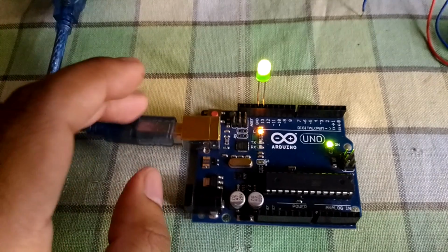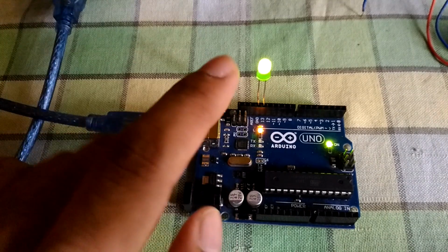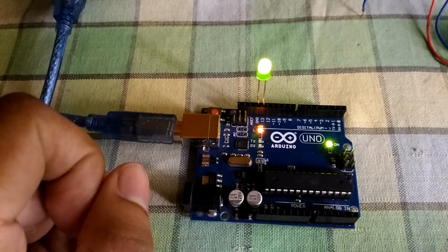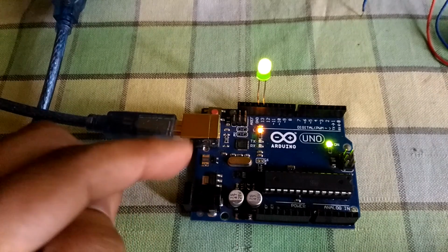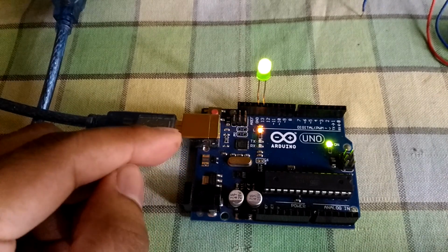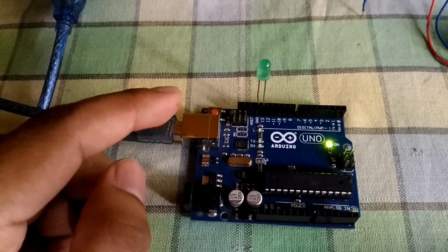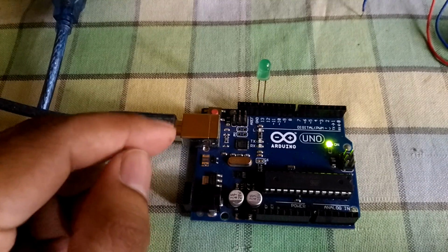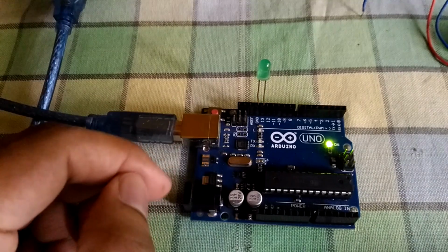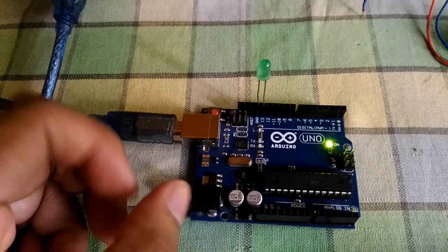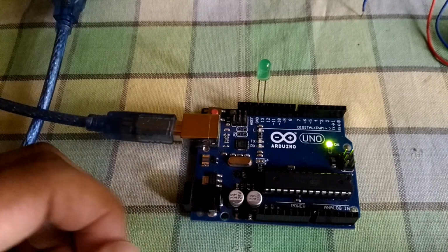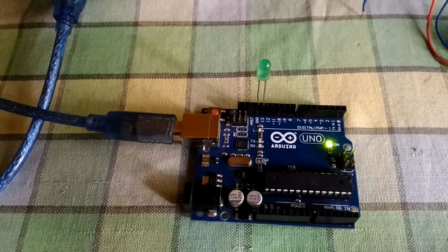And it's not only an LED. As you can see, I have connected a buzzer to show you it can be a motor, but never connect a motor to your Arduino directly. Pass it through a motor driver circuit, because an Arduino can only handle up to 40 milliamperes, but a safe current level for Arduino is 20 milliamperes, and a motor to spin draws much more current than 20 milliamperes. So that will damage your Arduino in the long run.